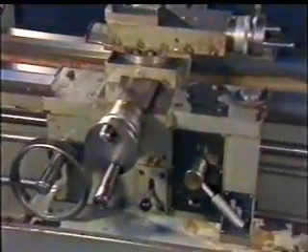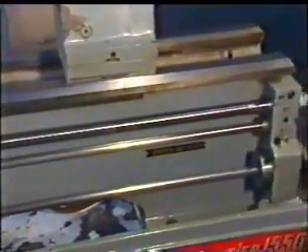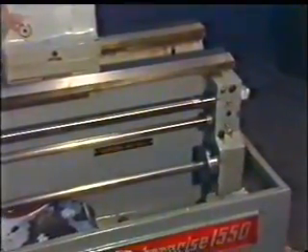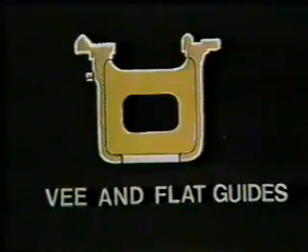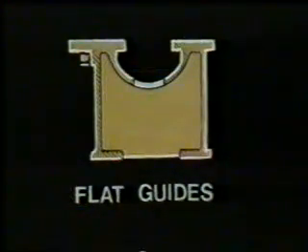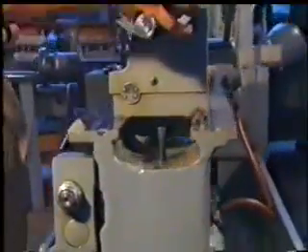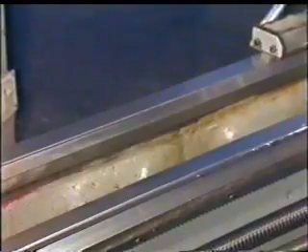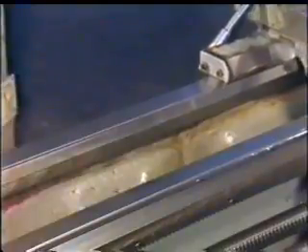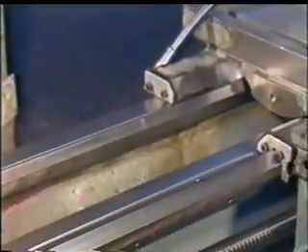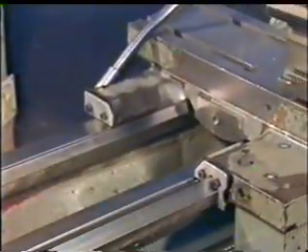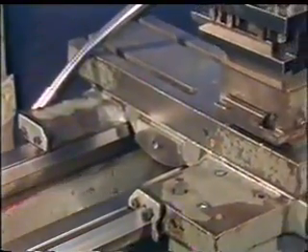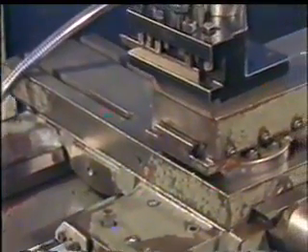The bed of the lathe forms the body structure supported on legs. It is cast with a box-like cross-section provided with V and flat guides. The guideways are finely finished to have a perfect bearing for the carriage and other accessories to slide freely.